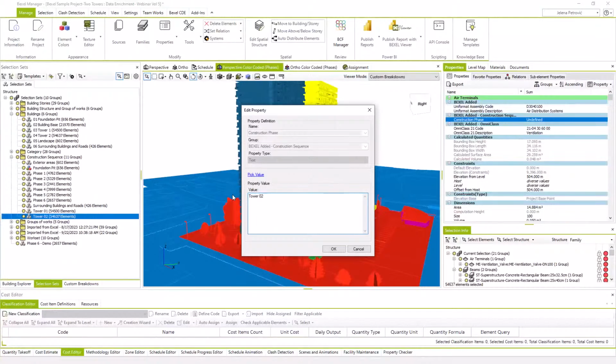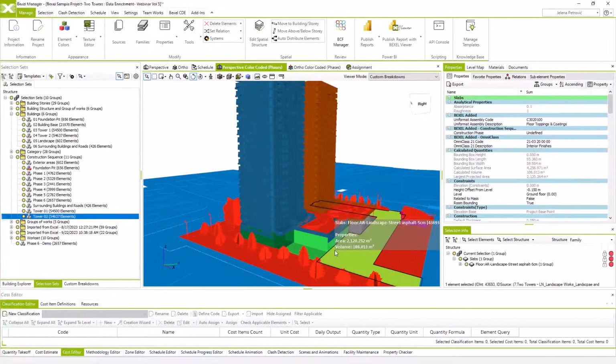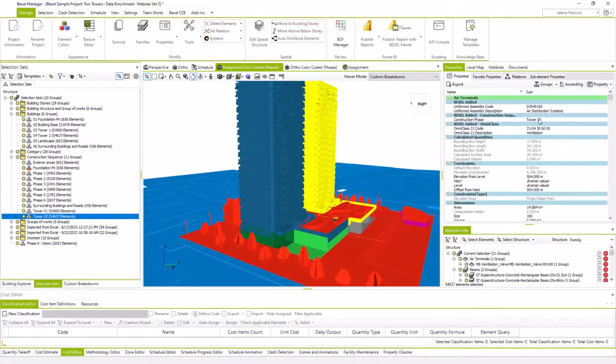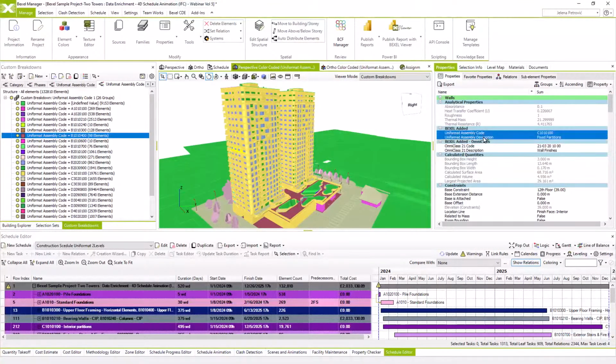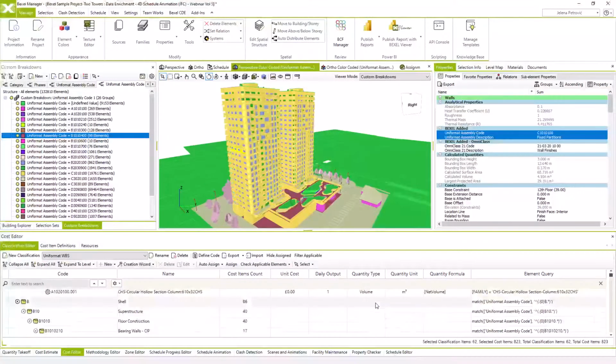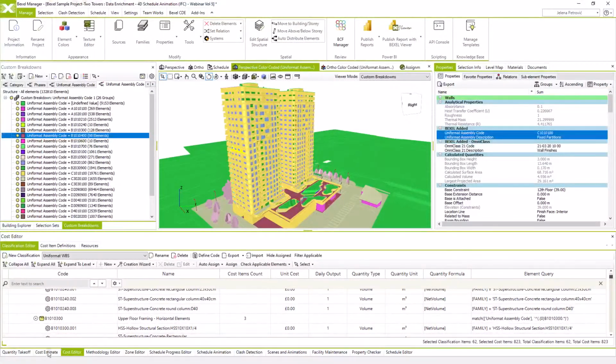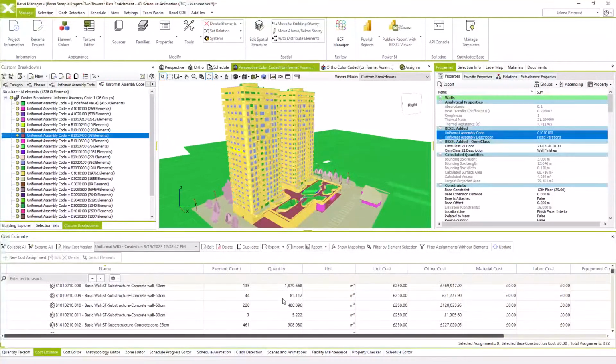Okay, I have manually entered values for the property related to project phases. Now I'm going to switch to the BIM model I used during the last session. During the last 2 sessions, actually, we went through the 4D, 5D BIM planning workflow on an example of a high-rise project based on IFC, which originates from the Autodesk Revit authoring tool. The BIM model has been enriched with classification codes. In our case, UniFormat classification was used, which was used for generating work breakdown structure based on classification code rules and used for construction work items creation based on the UniFormat work breakdown structure.